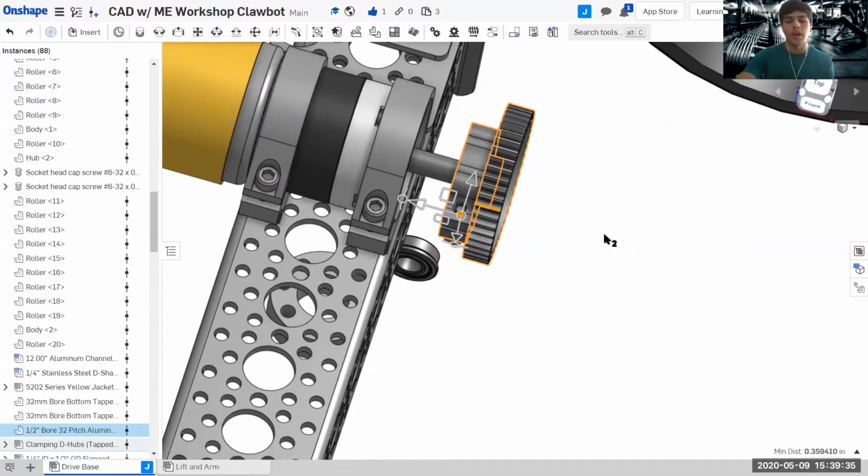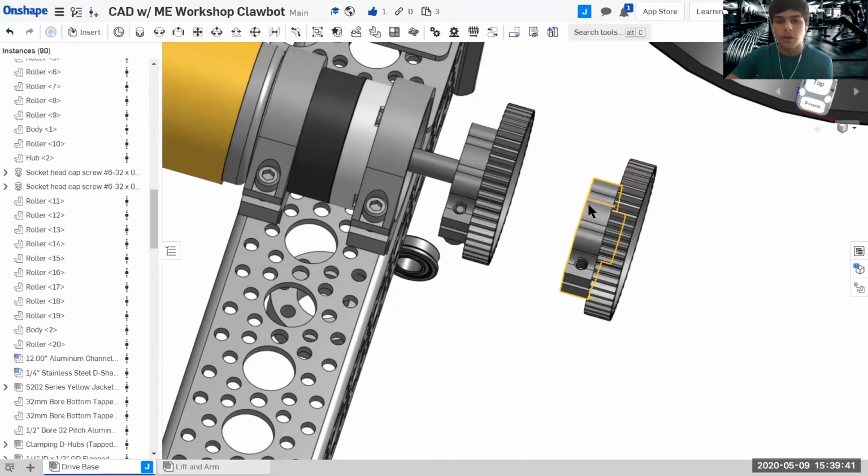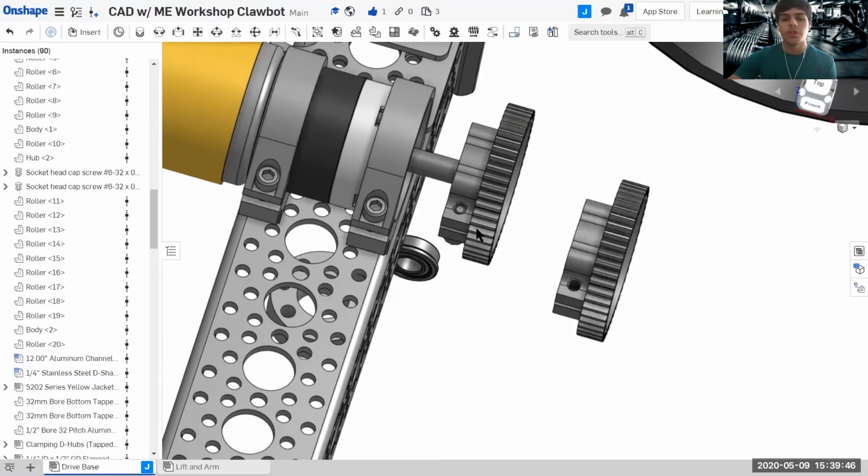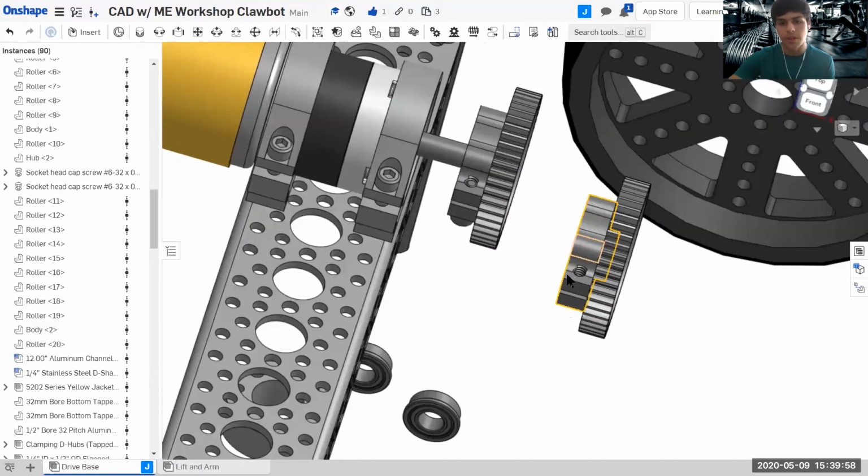Once I've done that, I deselect the parts that I copied, and then I hit paste. And if I did it right, yep, these. So that's the cool thing. Also, the copy paste option is kind of replicate, except it doesn't put the mates in a certain position. But you basically copy 2 parts. If they're fastened together, then that mate will also be together. So that's a really helpful feature to know.